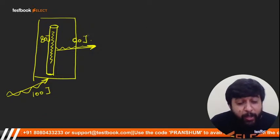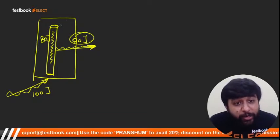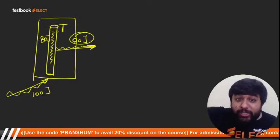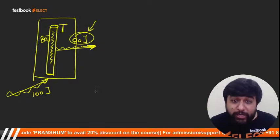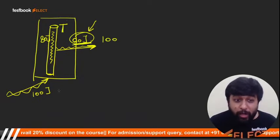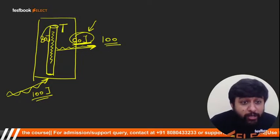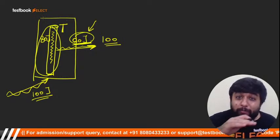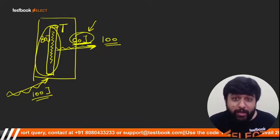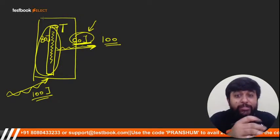The amount of energy that goes out by radiation depends upon the temperature of the rod. As the temperature of the rod increases, this value will also increase, and a time will come when this value will become 100 joule. So you are supplying 100 joule, 100 joule is going out, and nothing is stored in the rod. So the temperature of the rod will become constant. At that time the electric heater is operating at steady state.